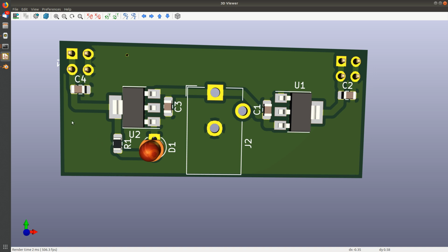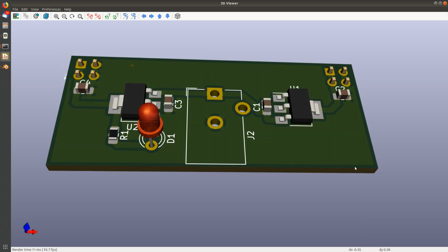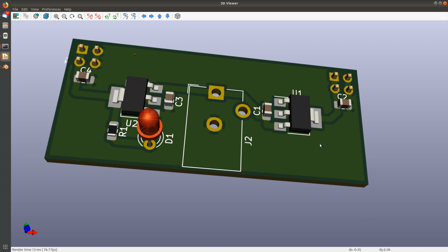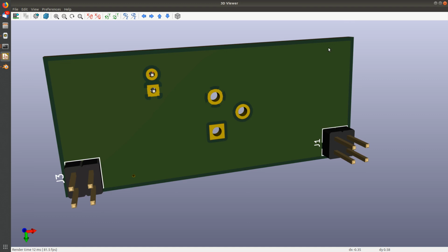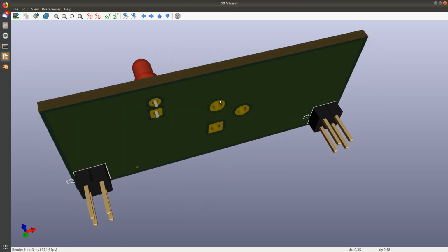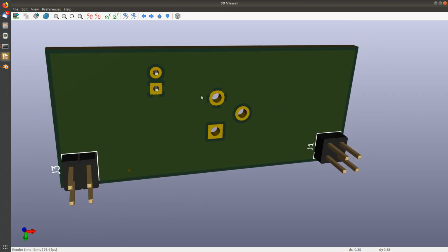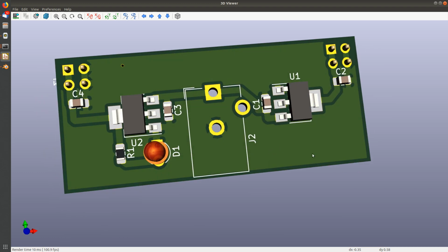But normally I do it because if you have high frequency chatter and signals running around on these boards, they need to go somewhere, or they'll radiate off and cause you problems in advanced designs. So normally you see people putting vias around the outside of these boards so that if any stray currents and voltages are flowing through the copper over here, if it can't get to the ground this way, it could bounce to the back side of the board and get to the ground over here. The rule is, you want to keep these two ground planes well connected, and you don't want RF signals wandering off the boards.